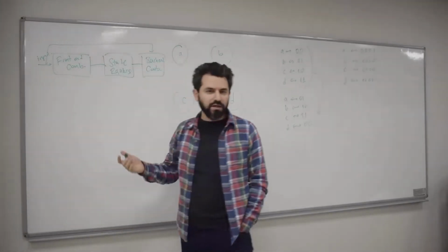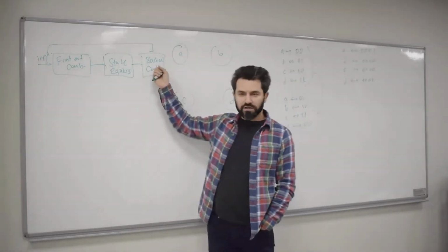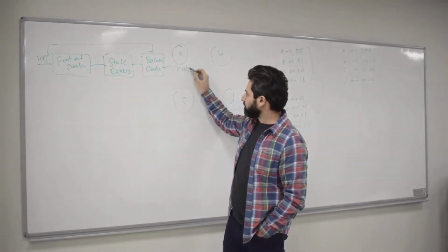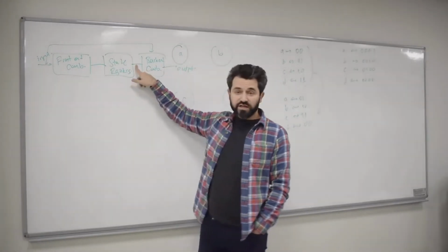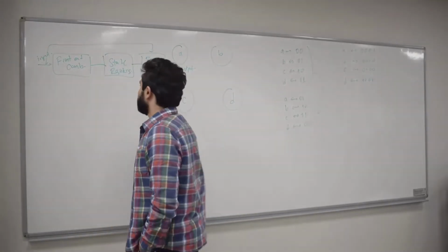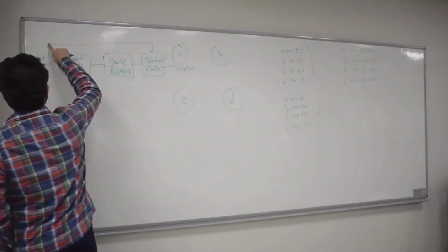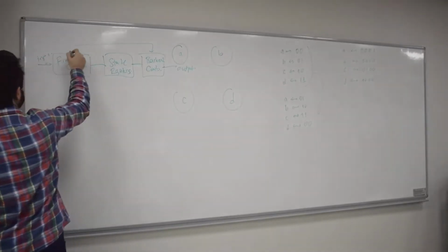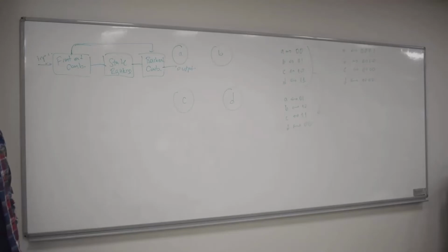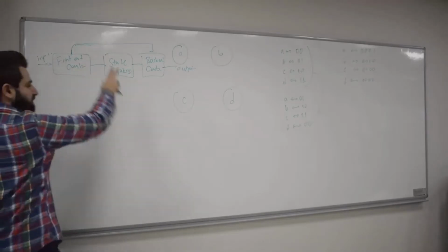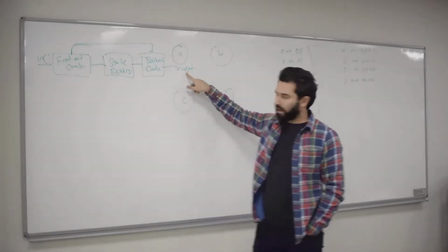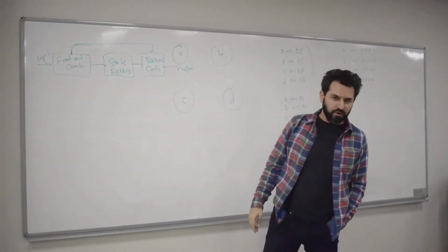And then we call it Mealy, right? The Mealy circuit is where the output here is a function of state values as well as the input, okay? Or maybe not entirely the input, but maybe a function of input, right? That might be a possibility, that it goes through the front-end combinational circuit and creates a value to be used by the back-end combinational circuit, and we get an output, okay?